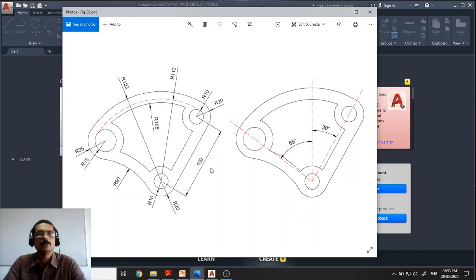Of course, as I mentioned earlier, you can do it with a different procedure, but I just want to show you some editing commands and some drawing commands also. So I'll be using this arc, and from there I'll be preparing these circles. Once these two circles are produced, I can draw the outer circle. Then it is relatively easy. I'll be using the offset command in the later stages, which you may be familiar with, for creating parallel objects. For initially drawing the line and other things, we'll be using rotate with the copy option and the rotate option.